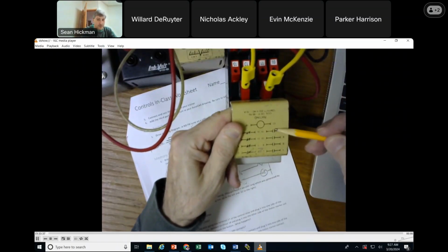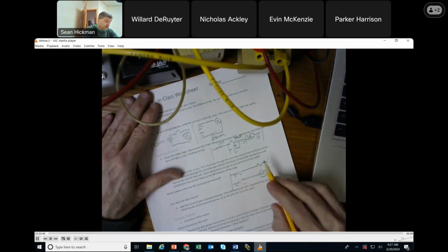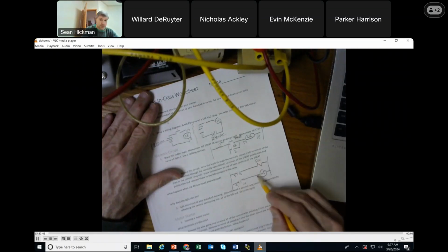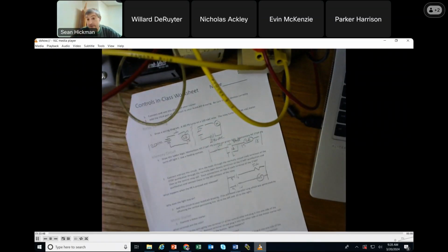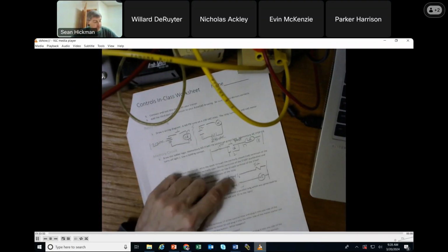All 4 of these close. So it's like 4 switches. And we could use 1 switch for the memory, 1 switch for the solenoid, 1 switch for the motor starter, you know. So that relay can turn on a variety of different things if I hit the start button. Is this making sense here?